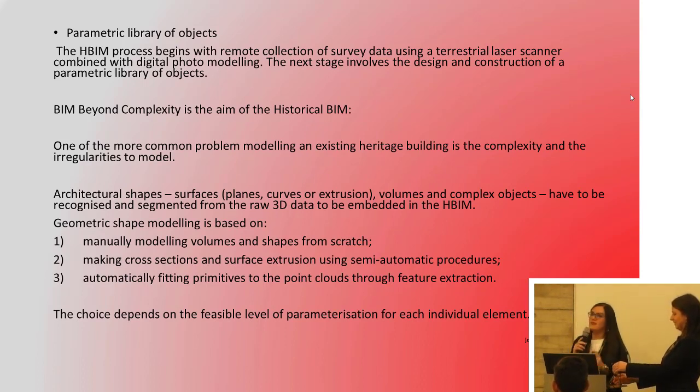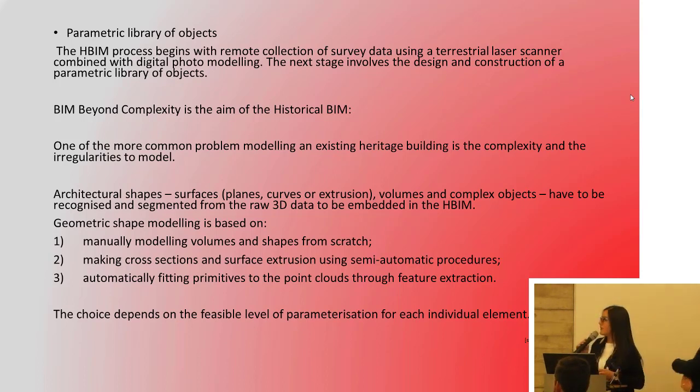So the interesting thing in delivering a heritage building with Revit is to create a proper library. So you are delivering the model, but also the library with all these objects that are just of that building. So the columns belong just to that building, and you can do this using the point cloud. It's very easy and very useful, because you can get a section, get a profile, and then you can create an ad hoc family for this kind of building.